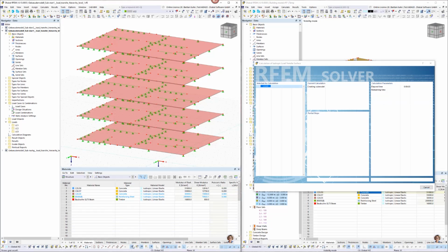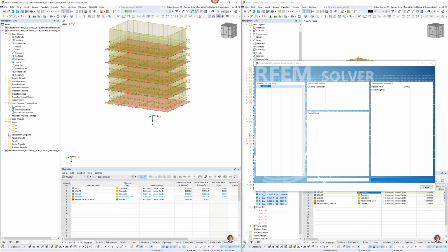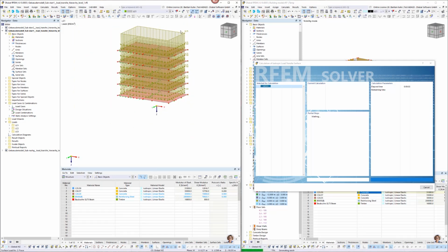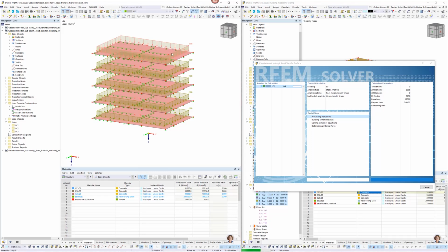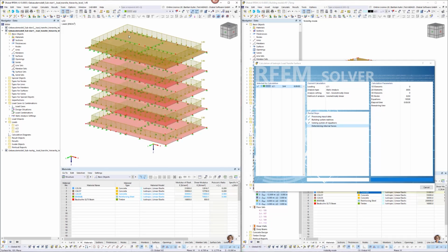And here we will also look for the load case 1 with the force on it. So you see here load case 1, we have the weight of it, or maybe we will go to the load case 2. Actually, I think that is better because we do not have the self weight of the quite heavy concrete in it.